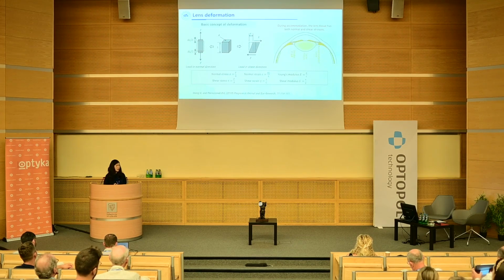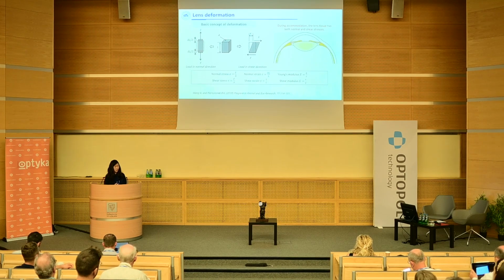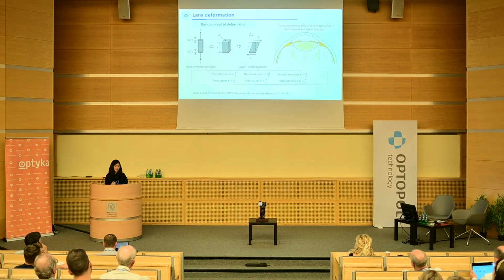If we want to describe a material's behavior independent of its shape, we need to involve the concept of stress and strain. Stress is the force applied per unit area, and strain is a unitless concept describing deformation. There are two sets of equations for the normal and shear loading conditions because the directions for some terminologies are different in these two conditions.